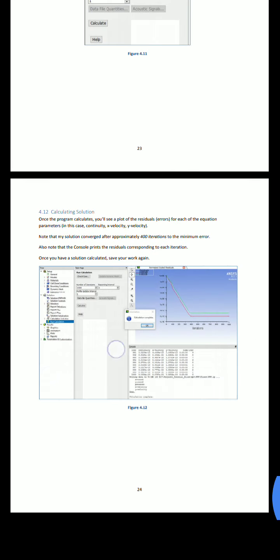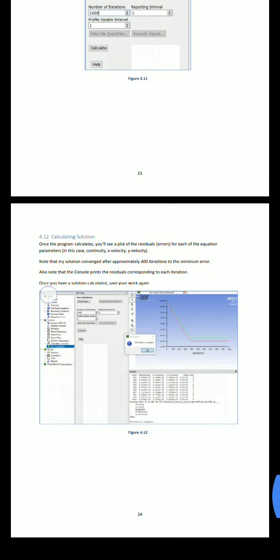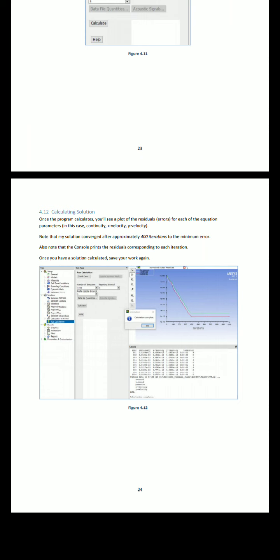So after solving this, we can go to the post processor just to see the result. Velocity contours: you can see the velocity we applied. The same velocity is coming at the outlet. And in laminar flow, the boundary layer is there. The boundary layer will disturb the flow. So in the middle you have 0.1 meter per second, and on the other side you may have lower velocities.